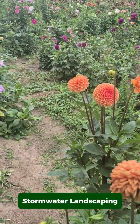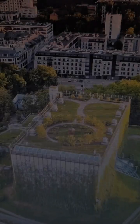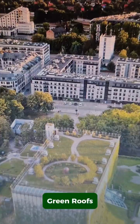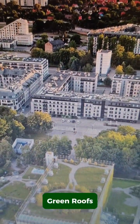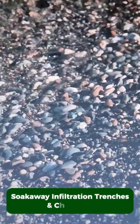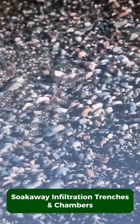stormwater landscaping, which is one of the most affordable methods. It produces cleaner runoff, requires relatively simple maintenance, and creates attractive green spaces; green roofs, which are specifically engineered rooftops covered with vegetation. They absorb rainfall, improve air quality, reduce building energy costs, increase biodiversity, and reduce the amount of stormwater entering drainage systems; rainwater harvesting, where rainwater from rooftops is collected in storage systems for future use, reducing the demand on municipal water supplies; and lastly, soak away infiltration trenches and chambers. They're underground stone-filled reservoirs that temporarily store runoff and slowly release it into the surrounding soil. Together, these systems mimic nature and significantly reduce flooding.